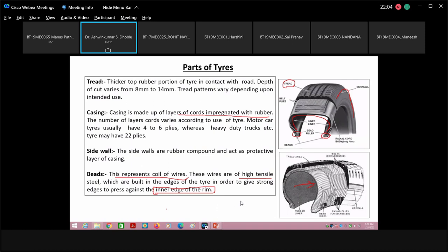Therefore, for rubber hoses also, it is recommended not to use oil for fitment of the rubber hose onto the ports. Better to use water rather than oil. So if he is putting water, don't say anything, but if he is putting oil, please be careful that putting oil on the rubber part is not advisable.